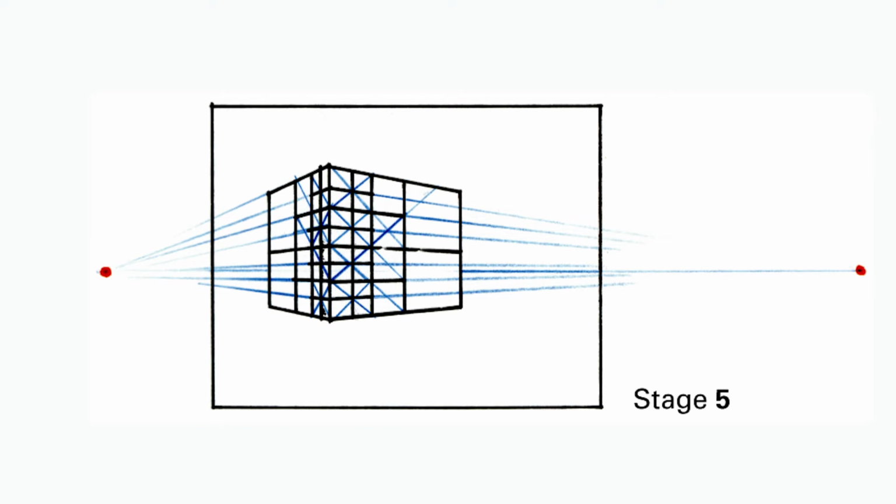You have just divided up a box frame, and you can use this method conversely to duplicate spaces, using the box provided in exercise sheet 4.4. First, double the height of your box by doubling the length of the vertical measuring line. Then draw the new box you have created in perspective as you did in your first perspective exercise.